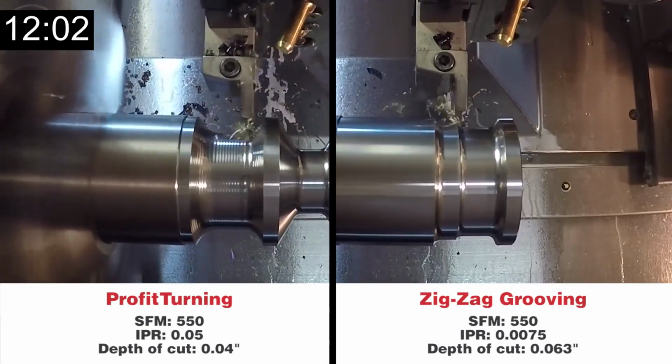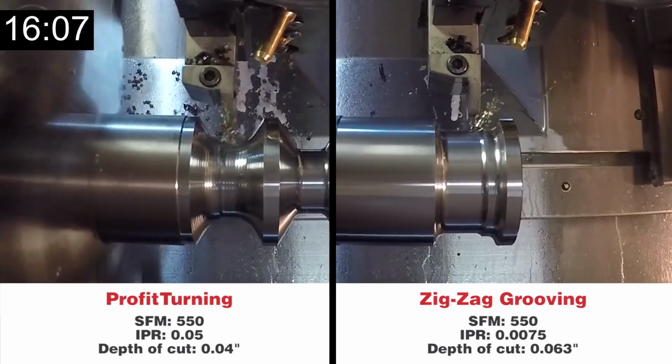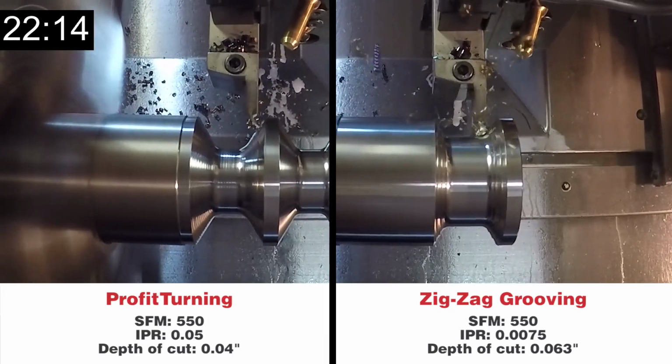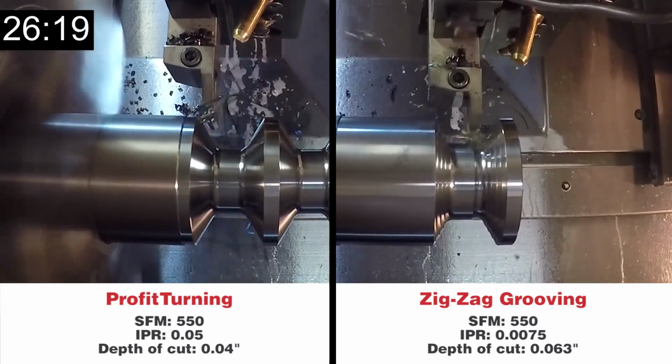All right, so what we can see here is Profit Turning on the left, and then your traditional toolpath on the right. With Profit Turning, you can see really good chip breakage. It's controlling that chip load and the tool engagement. On the left, we're already at the finish pass, and on the right, the traditional is still working down.